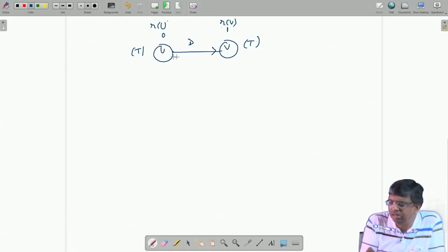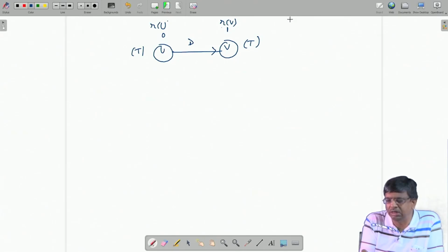This is required here only in the next cycle, not in the same cycle. So t will be good enough: in one t amount of time it does the job here, then in the next t amount of time it works on that, and at that time it prepares output for the next cycle operation here. So the two times do not get added, and the critical path is now equal to t.